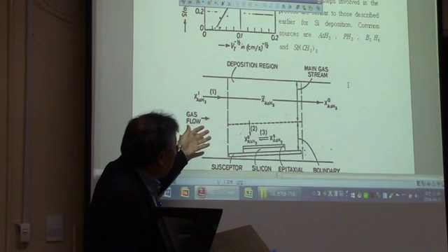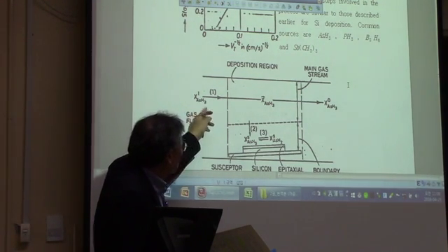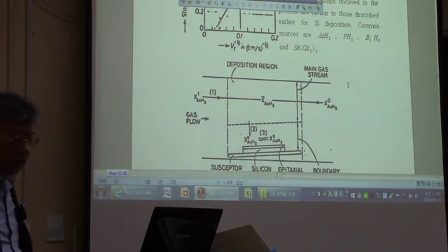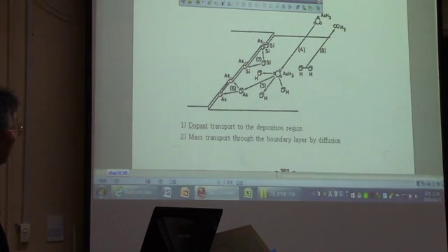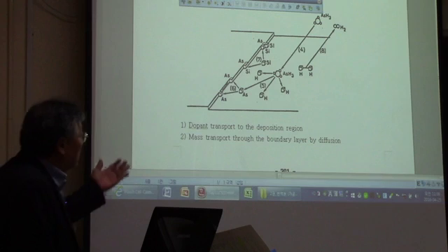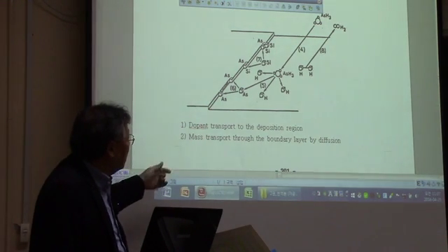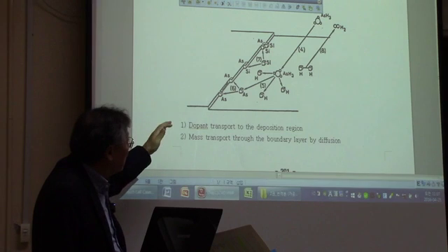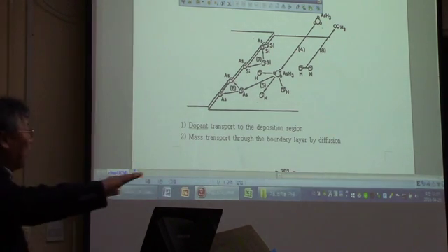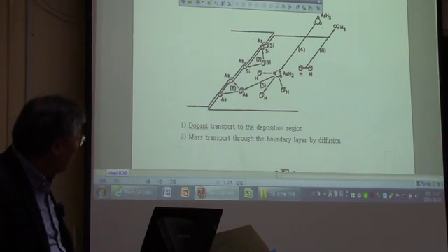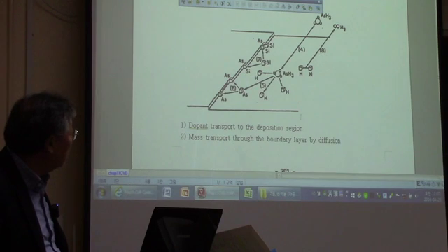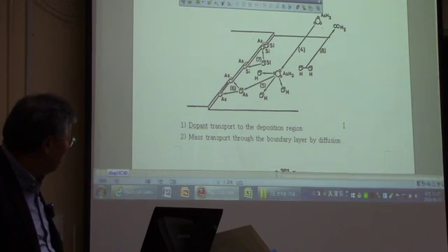When you grow an epitaxial layer, you just put in the dopant gas, like arsenic, phosphorus, boron, and antimony. You can see all those things. And then it's more or less like silicon epilayer growth. Using the kink site, layer by layer, the silicon film is going to be formed on top of a single crystal silicon. That's the epitaxial growth.